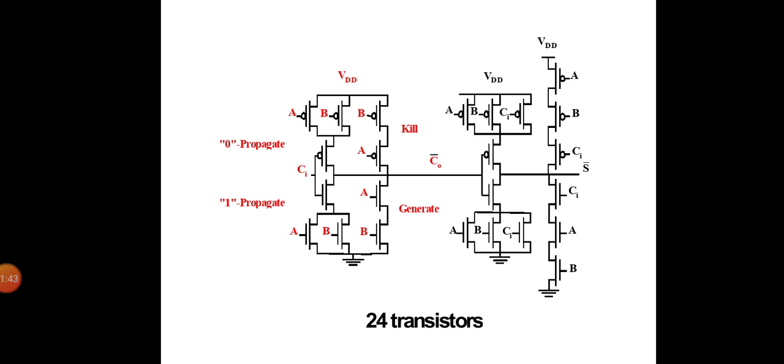This results in a considerable reduction in both area and delay, and the analysis of the sum circuitry is left to you, and you can observe some of the points. That is, this full adder requires only 24 transistors, and the NMOS and PMOS chains are completely symmetrical, which still yields a correct operation due to the self-duality of both sum and carry functions. So as a result, a maximum of 2 series transistors can be found in the carry generation circuitry.